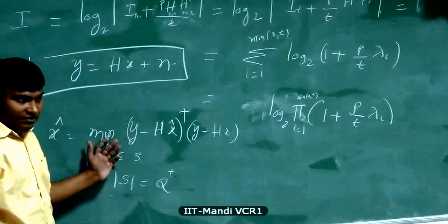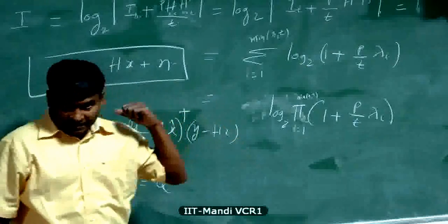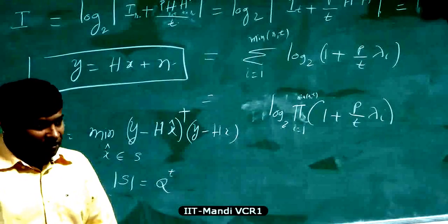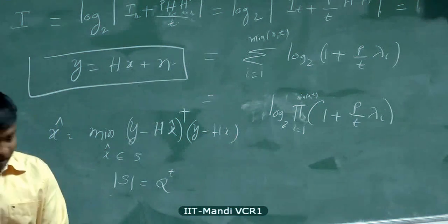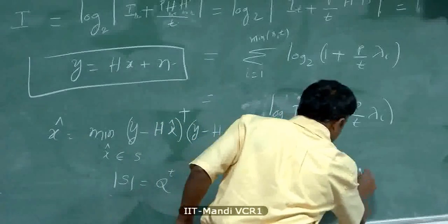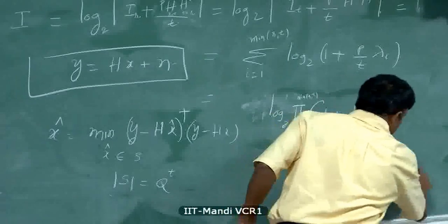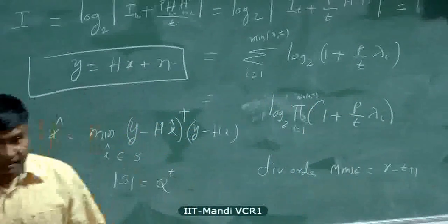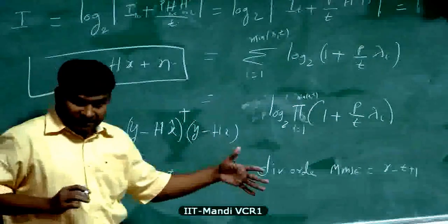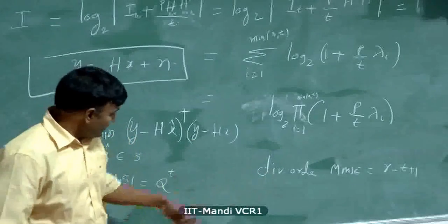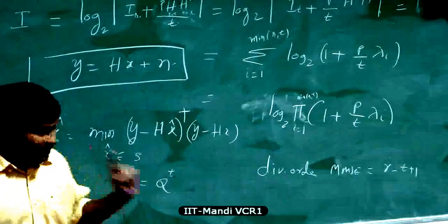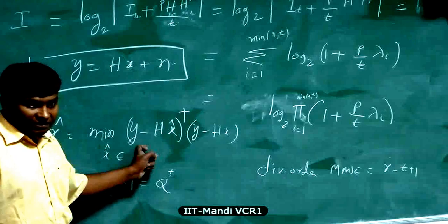So, a maximal likelihood receiver will give you a performance better than the MMSE receiver we discussed, and in fact you can show that the diversity order of MMSE is NR minus NT plus 1, or R minus T plus 1, and when R equals T, it has first order diversity, whereas this maximal likelihood receiver can separate all the signals, that is like full interference of signal separation, but nevertheless it gives you full diversity of order R.